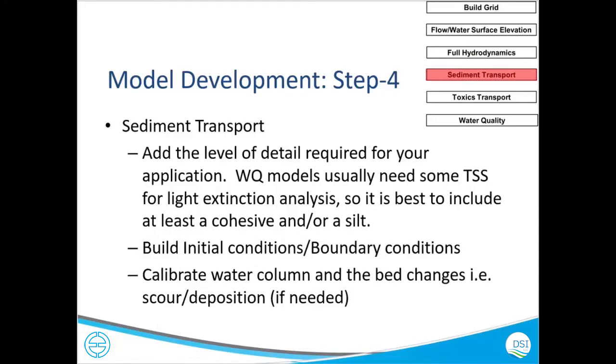So after you have your hydrodynamics right, now if you want to do sediment transport, it's the right time to move to sediment transport. Then you define how many classes of sediment you want to use, if it's silts, if it's sand, or if it's clay. Based on that you define your boundary conditions and your grain size distribution on the domain.